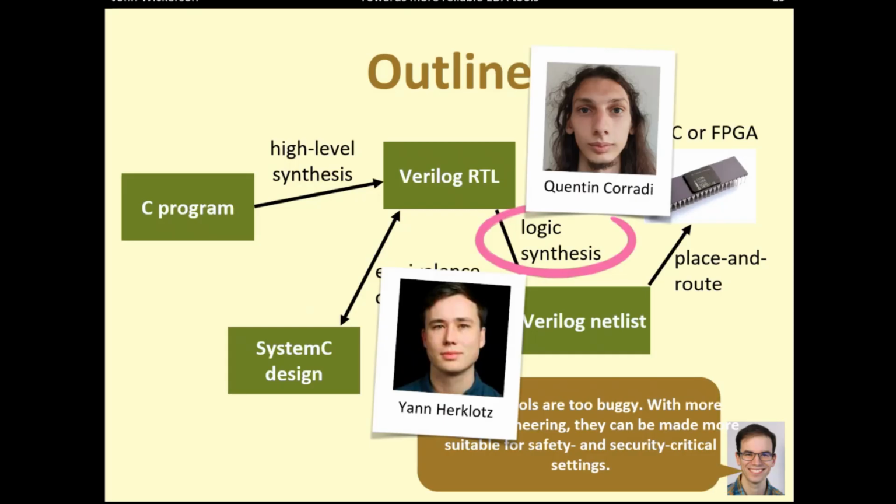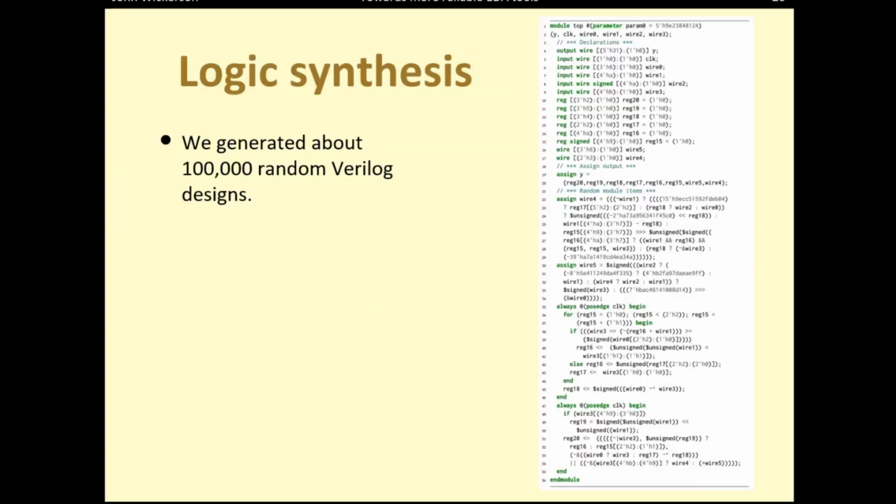I want to talk next about logic synthesis, so a bit further down in the tool flow. This was also some work done by Yann and also my other PhD student, Quentin. The story is actually fairly similar. We generated a whole load of random Verilog designs. They don't have to do anything, but they have to be legal and valid. Here's an example of one of them. I'm not going to go through it, but you can see it declares a whole load of nonsense wires, does a whole load of nonsense assignments,